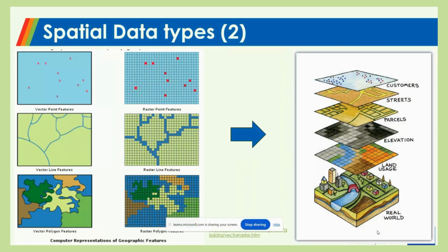And some basic data structures for raster files are TIFF files, as they're called, or JPEG, it's still a raster image, or GeoTIFF. But the TIFF images and the GeoTIFF images are geolocated. The JPEG image is not geolocated. We don't know the exact coordinates of each one of the pixels on a JPEG image on the globe. And that's the problem. We only know the coordinates on a Cartesian